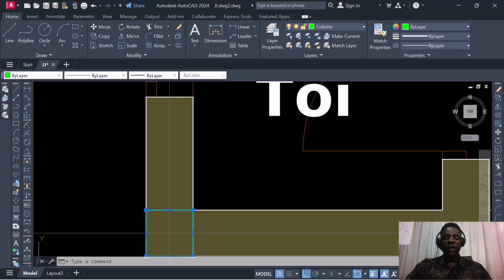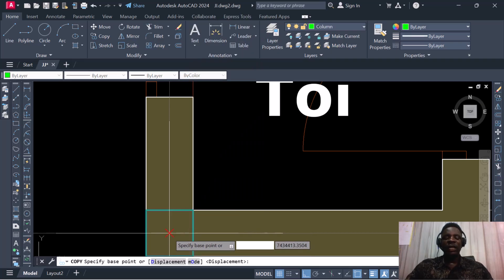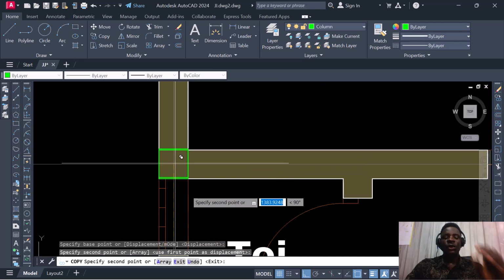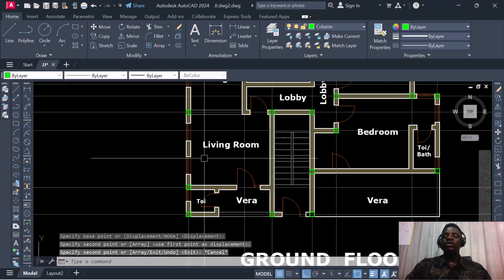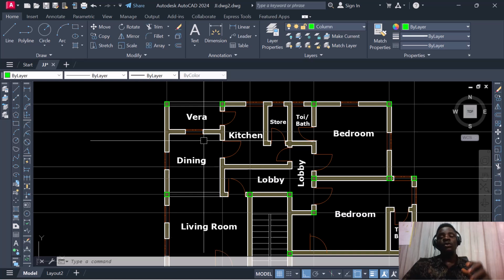All right, and another thing, apart from just considering a 5 meter interval, or a particular space in which you're going to introduce your column to support the beam, you're also going to look at what point you need to introduce a column for the sake of bonding, because you're going to look at the wall. Now you're looking at how the whole structure will be stable, and how to insert the column such that it supports the structure well and still bonds suitably to the wall.